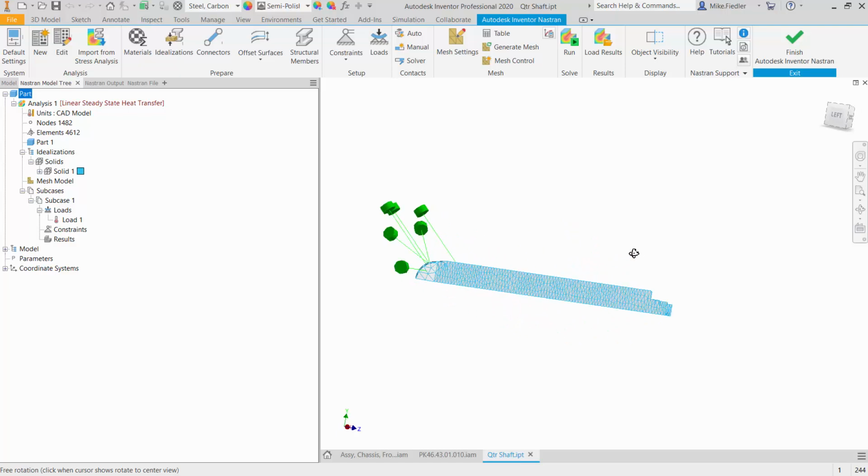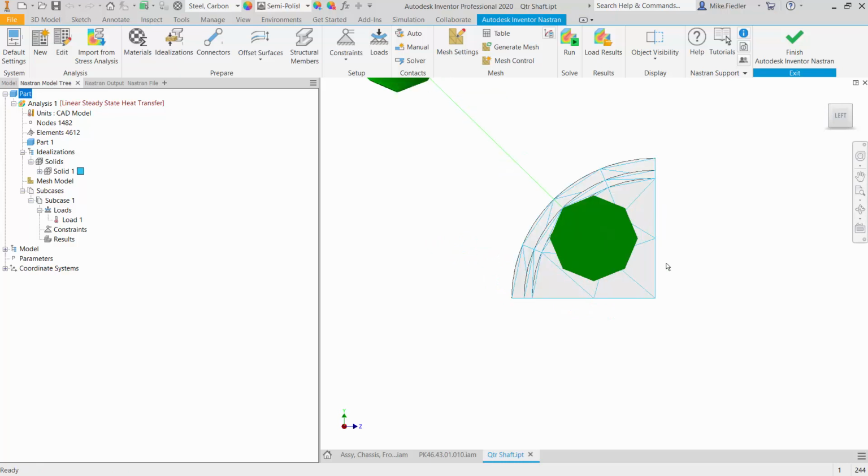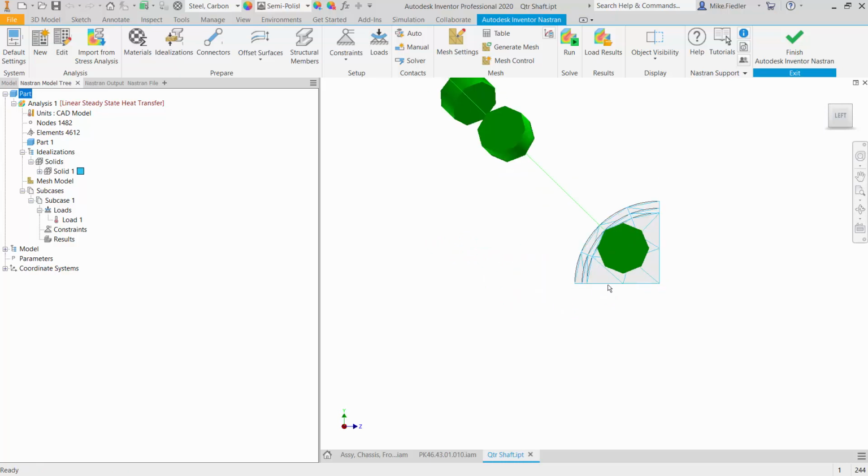And one of the things I should mention is due to symmetry, and this was covered in one of our other courses, one of our other videos, due to symmetry, I've cut away 3/4 of this model, right? Because given what I'm going to do on it, what happens in this quarter of the model should be the same thing that's happening in this quarter, and so on and so forth. So this is really going to give us a couple different benefits.